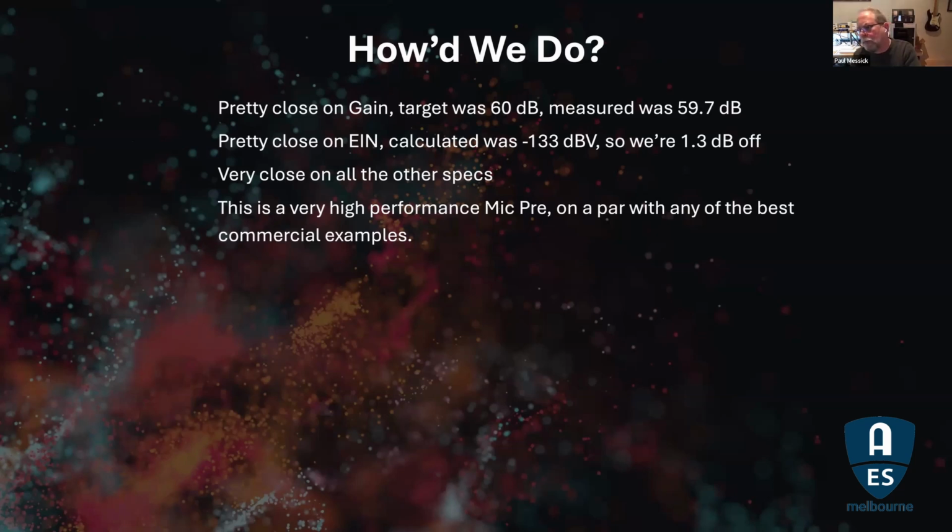I find more recently that's been less important to do, but it matters more for things like the voltages that drive the analog part of ADCs and DACs and things like that, because they actually tend to not have very good PSR there. Does that answer that question?